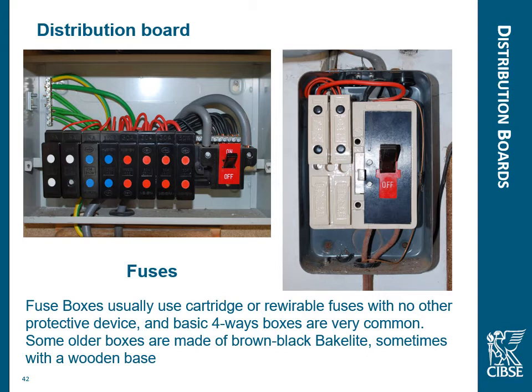We can see the colours dictate red a 30 amp, blue 15 amp, white 5 amp, and the different size cables getting larger from the right, smaller from the left there. These are the smaller loads like lighting, water heating, going on to ring mains and going on to probably cookers or perhaps an electric shower, obviously in a domestic location there.